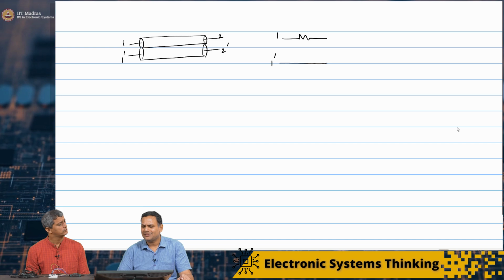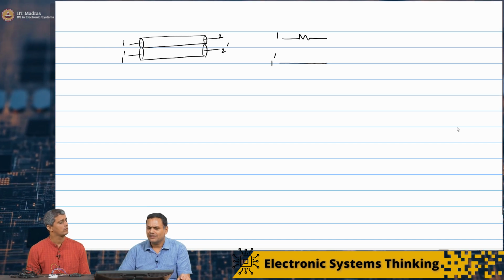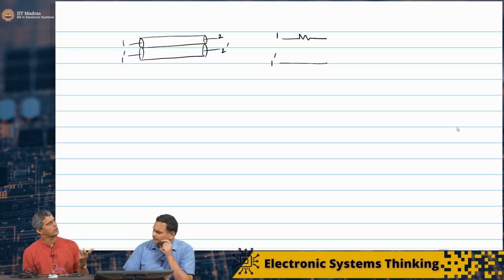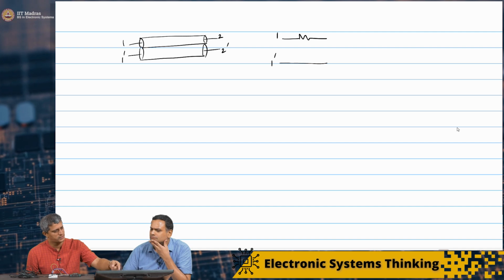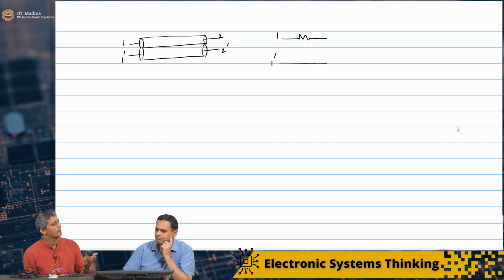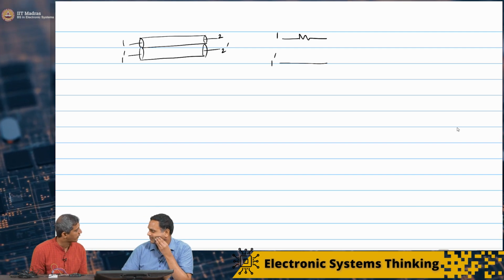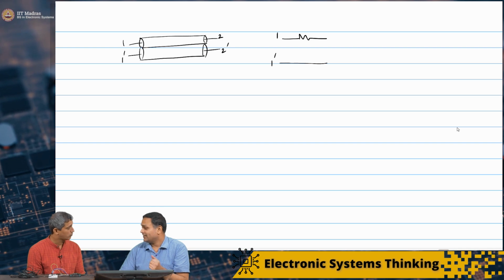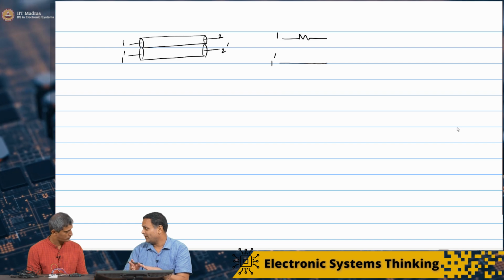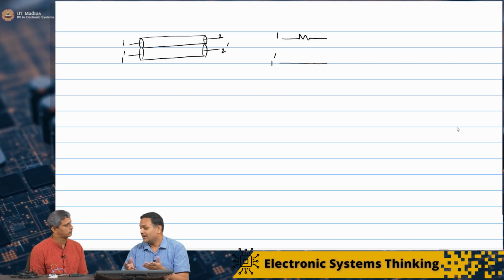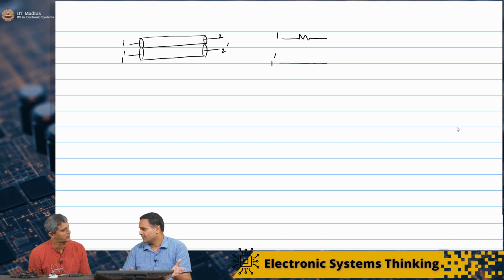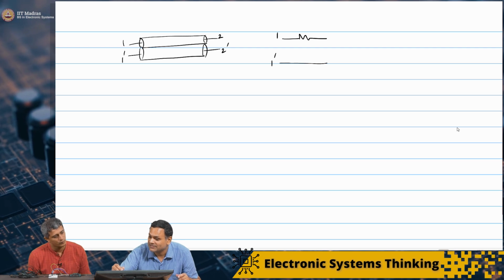My guess is that these two wires are separate. One other question is, you justified resistance. Now, even if it was a very complicated resistive network, you cannot have frequency dependent effects. So one guess immediately is I have two wires, and now they have some rubber or something in between, which may have some dielectric constant. So my guess is that there's going to be some capacitance between them as well, some unwanted capacitance. So maybe I will add some unwanted capacitance as well.